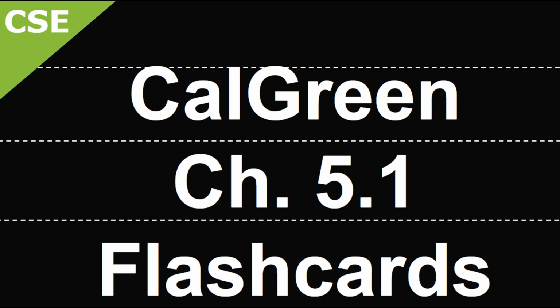If 151 to 200 total actual parking spaces, then 35 are required to be EV-capable and 9 EV charging stations. And finally, if 201 and over total actual parking spaces on a new building project, then the number of required EV-capable spaces is 20% of the total number of actual parking spaces, and the number of EVCS is 25% of that total.